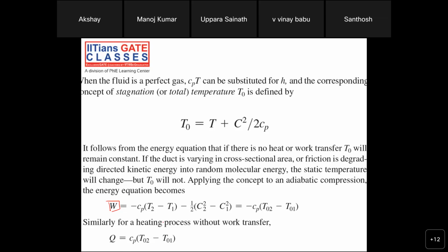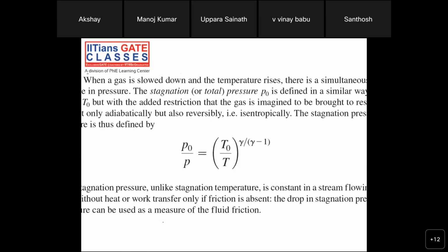That is the fundamental prerequisite, I can say, to study propulsion as a subject. That is why these quantities are important when you define efficiencies and so on. You will constantly be replacing this term, whenever you have T naught by T, with the pressure ratio across the compressor, or the overall pressure ratio of a compressor, when it is given to you.